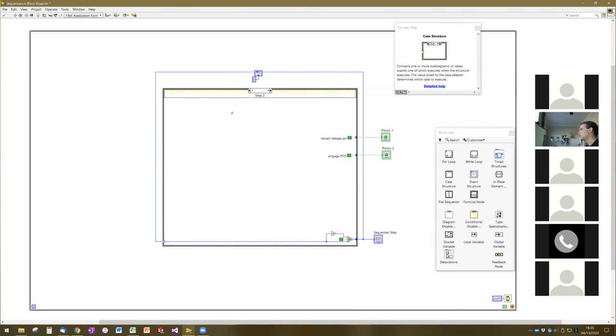Okay, so if we run this, both of these lights should immediately go green, and then we should count through the different steps, and then hopefully at the end, I think piston number 2 should go dark again. Let's see if that happens. With green, we're on step 1, step 2, step 3, and then on step 4, the piston retracts. Are there any questions about how this sequencer works, how we are advancing between actions and how we are changing the states of things that we care about?